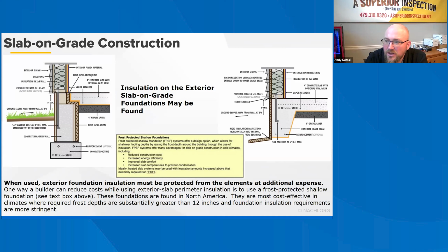This allows the thickened slab edge, the footing, to act as a moderately reinforced grade beam to reduce cracking from differential settlement. Concrete and masonry stem walls may be reinforced with horizontal reinforcement bars in a manner similar to that recommended for basement walls. For difficult site soil conditions, such as expansive or weak soils, other types of concrete slab foundations may be required or advisable, such as mat foundations or post-tension slabs.